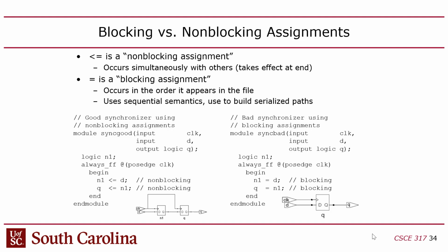That can get really confusing. You might say, what's confusing about that? It's just a data dependency. Well, in this case, it's pretty clear what's going on, but you have to keep in mind that this blocking and non-blocking is actually relative not to the inside of one module, but to the actual event, right? So in this case, the positive edge clock.